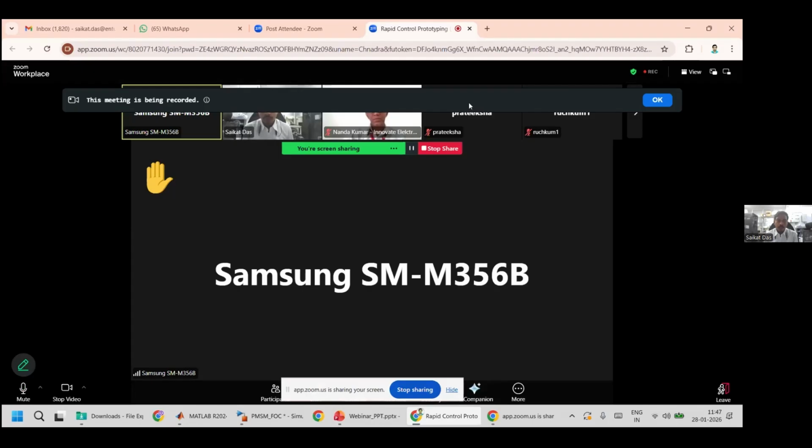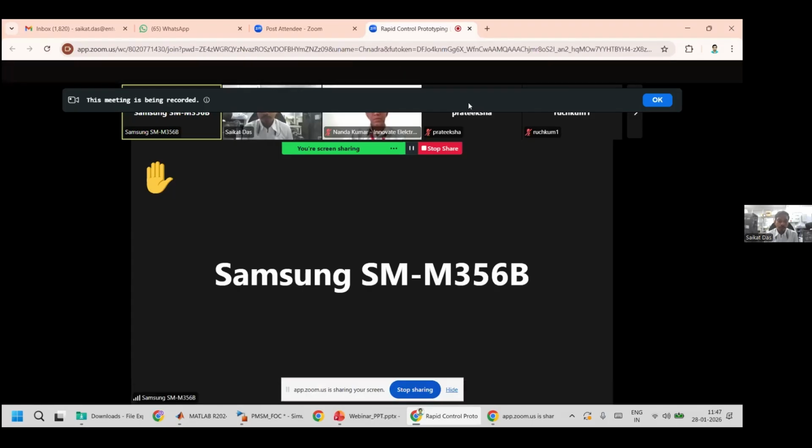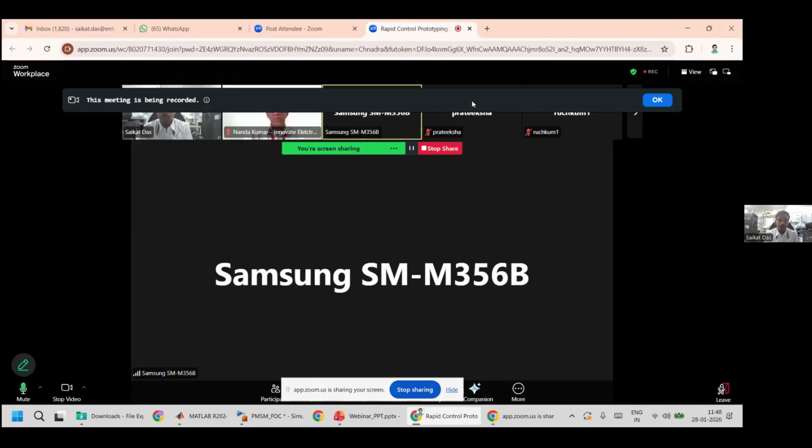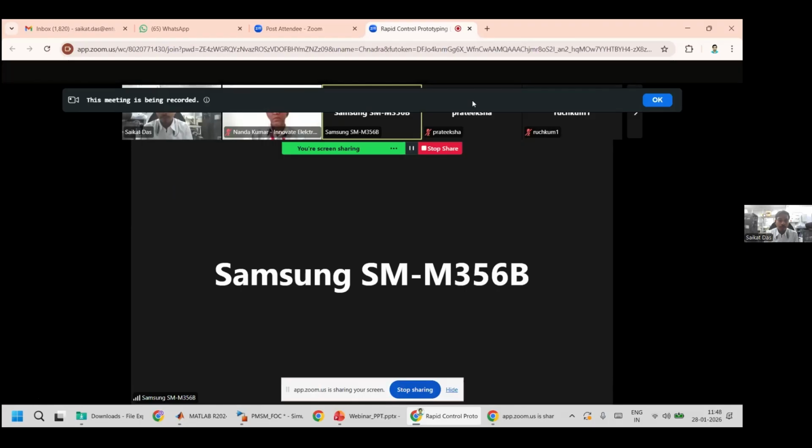Yes. And if it is coming with Hall sensors, then we are using the Hall sensor only for trapezoidal control. Trapezoidal excitation means two-phase excitation. We are taking the Hall positions based on the rotor, and we are estimating which phase you need to excite to make the rotor rotate or to get the maximum torque of the motor. Based on that, we are getting it.